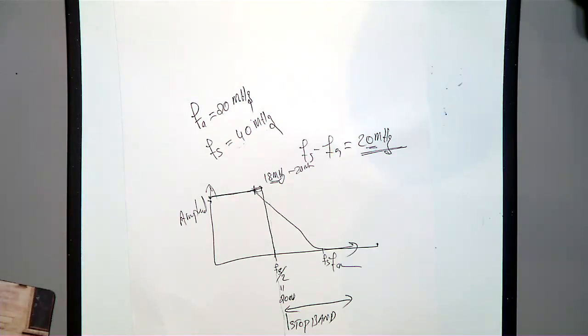Then what you really did is, you made your cutoff around the 3 dB point, around 18.5 or 19, and then you got a kind of slow transition. In your filter response, what is the stop band? You might have designed your filter. What is the stop band?